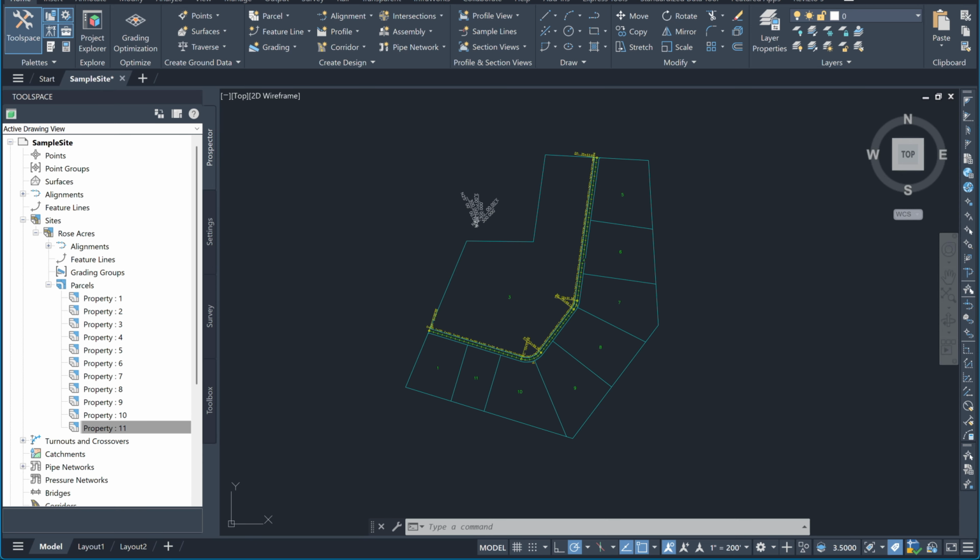The next important concept is drawing scale. Civil 3D understands that engineering drawings are ultimately created as construction documents. A drawing is not only displayed on a computer screen, it will eventually be plotted, printed, or exported into PDF format. Because of this, Civil 3D allows many objects to be controlled based on the drawing scale. This includes text size, label size, symbols, blocks, annotation objects.